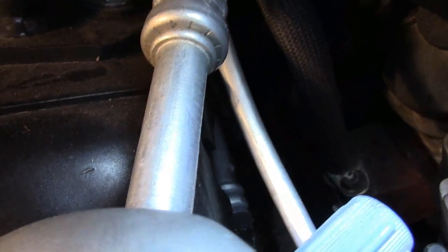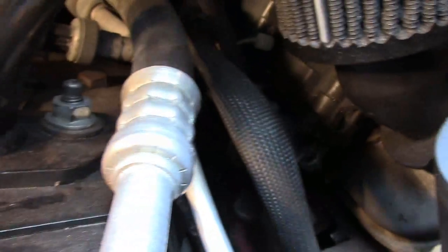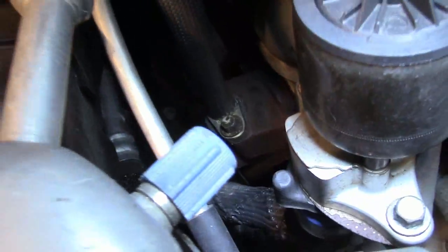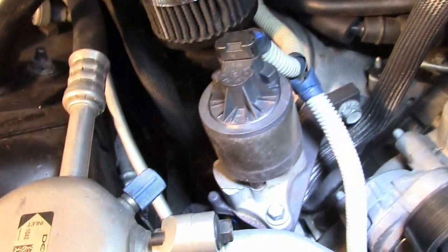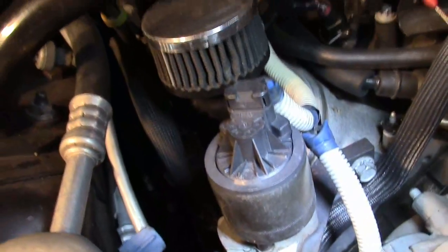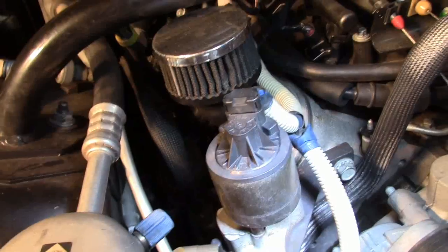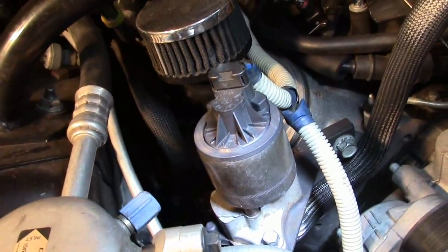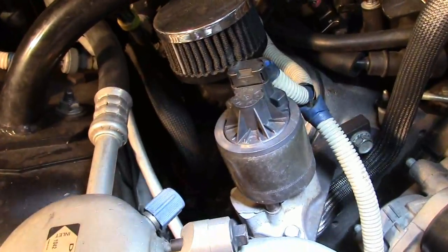There's actually another one directly adjacent and lower to it that also goes to the exhaust manifold. Let's follow that one, and it follows up to here, which is actually an EGR valve, an electric EGR valve. Now, how do we know that that's not part of the air system, even though it connects to the exhaust? Because there are no tubes connecting to an air pump.